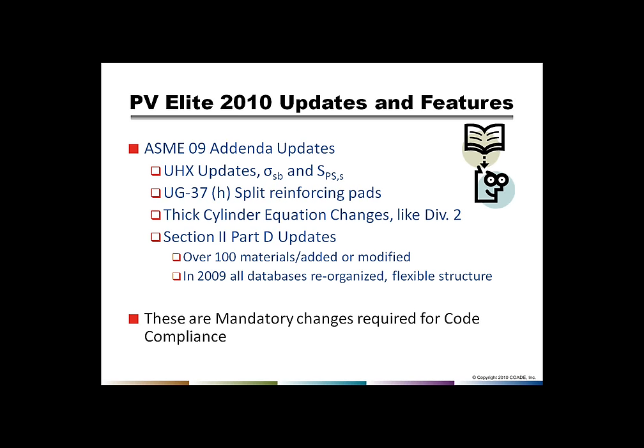Okay. There is an area calculation term in area of replacement called A5, which is the area in the reinforcing pad. And if your pad doesn't meet the guidelines for full penetration or where the weld is located, then you take a slight penalty of 75% on the area,